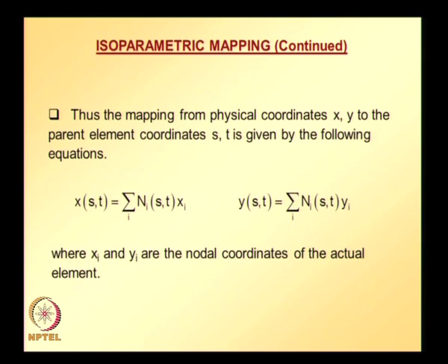So, shape functions are defined in terms of parent element coordinates, and xi and yi are nodal coordinates of actual elements. So, this is how physical coordinates x, y are mapped onto the parent element coordinates s and t.